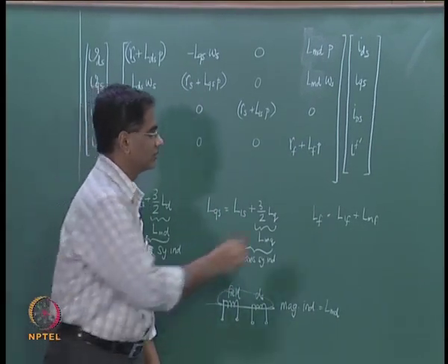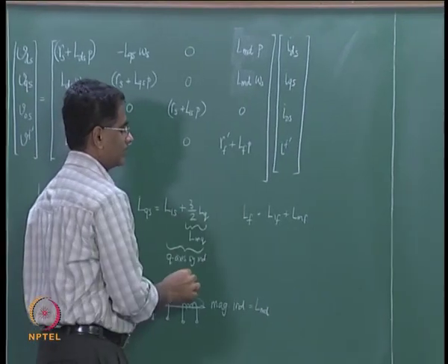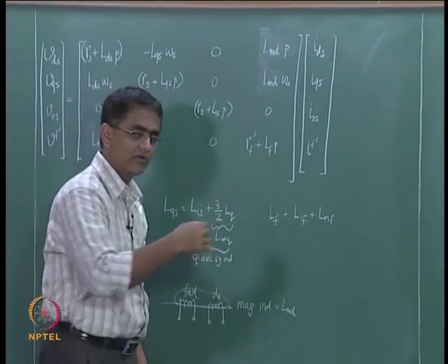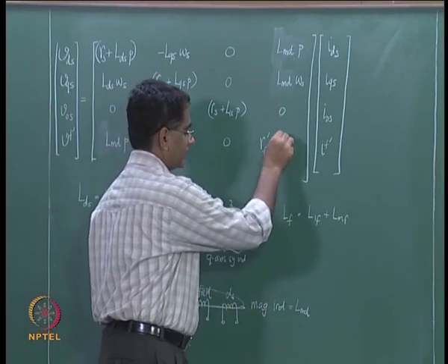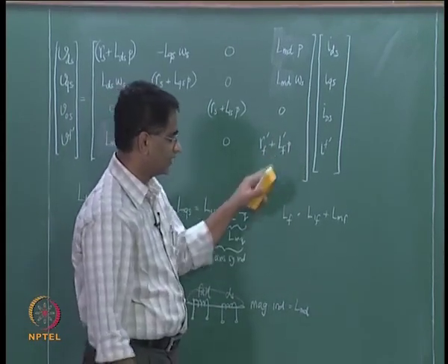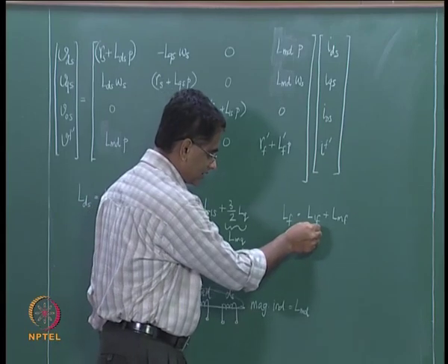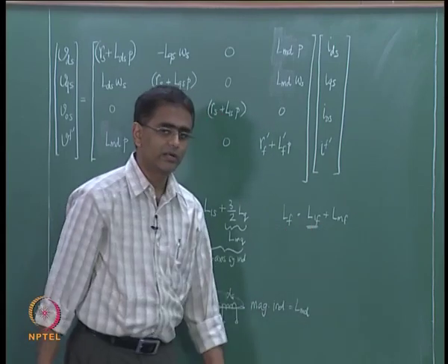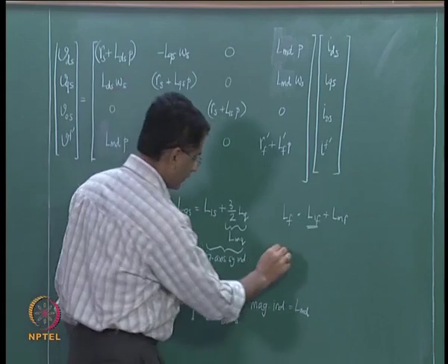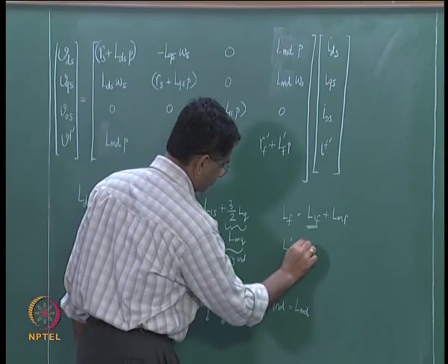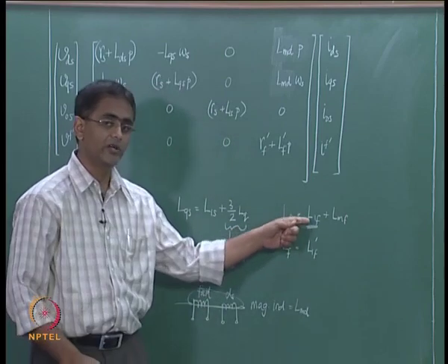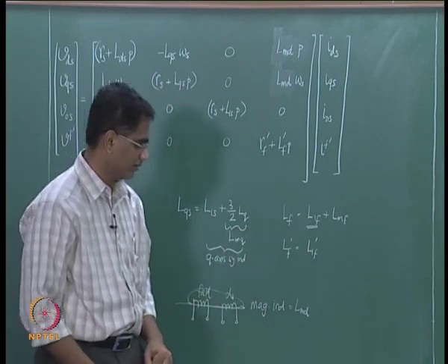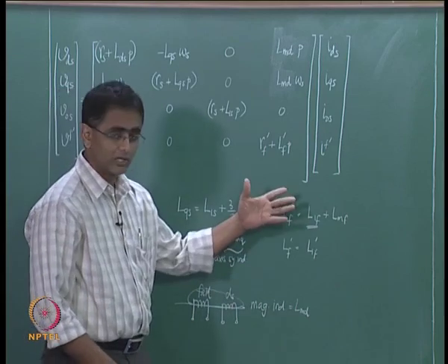to the stator turn, so it becomes then Rf dash, and Lf becomes referred by the turns ratio squared, which is again Lf dash. But in Lf dash what happens is the leakage inductance gets referred by turns ratio, so Lf dash is nothing but LLf dash, which is LLf multiplied by the turns ratio squared into 3 by 2 of course.